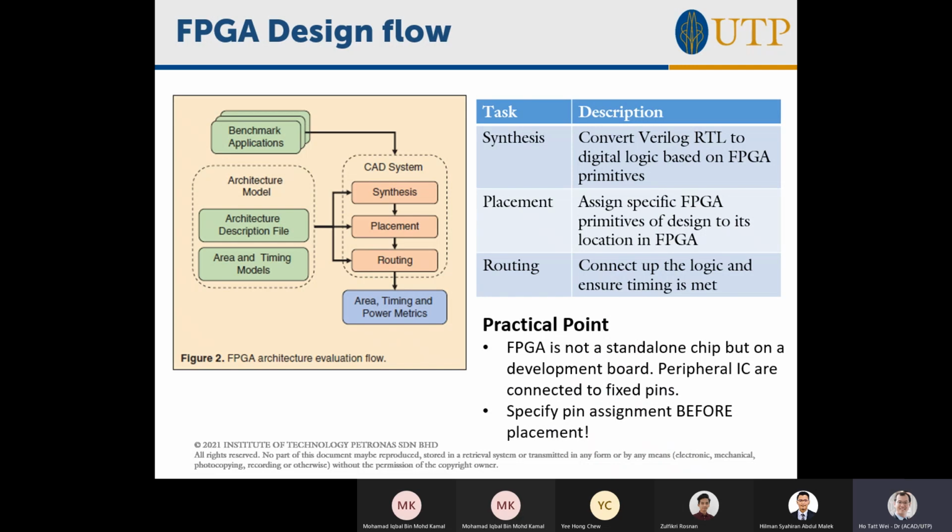They'll convert it in terms of the logic that can be made by the fab. For FPGA, it converts it into the basic FPGA elements, and these are basically the lookup tables, and we'll talk about that later. But here, I want you to understand that synthesis is just a process of translating your high-level register transfer logic from Verilog into a low-level digital function, which is implemented either as basic gates that the fab can make, or basic logic elements in the FPGA.